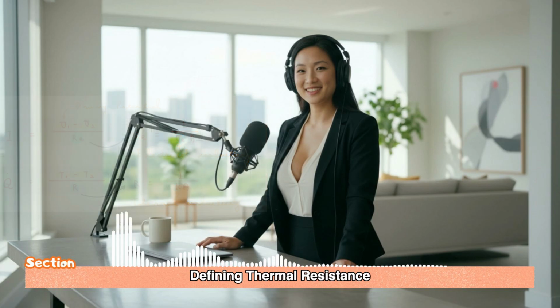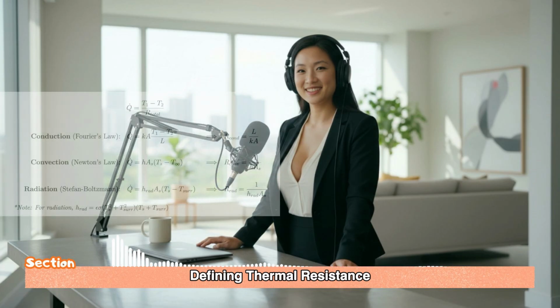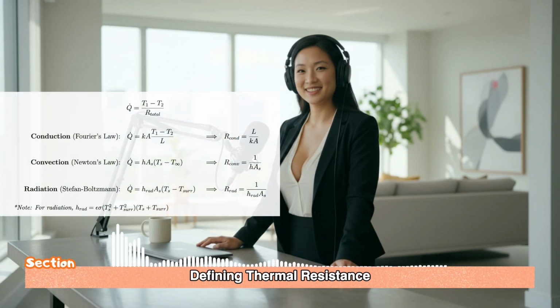Now let's define the three main types of thermal resistance that we're going to see in these circuits, starting with the most fundamental one, the conduction resistance for a plane wall, R wall. That resistance comes directly from Fourier's law, and it's defined as R wall equals L divided by kA. L is the thickness, k is thermal conductivity, and A is the area. This simple ratio gives you immense engineering insight right away. To effectively resist heat flow, to be a good insulator, you have two choices. You either increase the thickness, L, or you decrease the thermal conductivity, k.